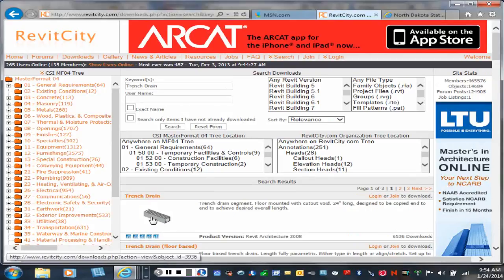Okay, so it shows a little section of a trench drain. This trench drain is a component. It's about 2 feet long. And these trench drains, that's the way they come. They're typically a composite shell with a metal grate on top, and they come in sections that you put together. Each section of this floor drain slopes a little more so that it ends up at the low spot. So when you order it, you would say, I need a 40-foot trench drain with the low point in the middle, and they will automatically deliver pieces that fit together that slope toward the middle.